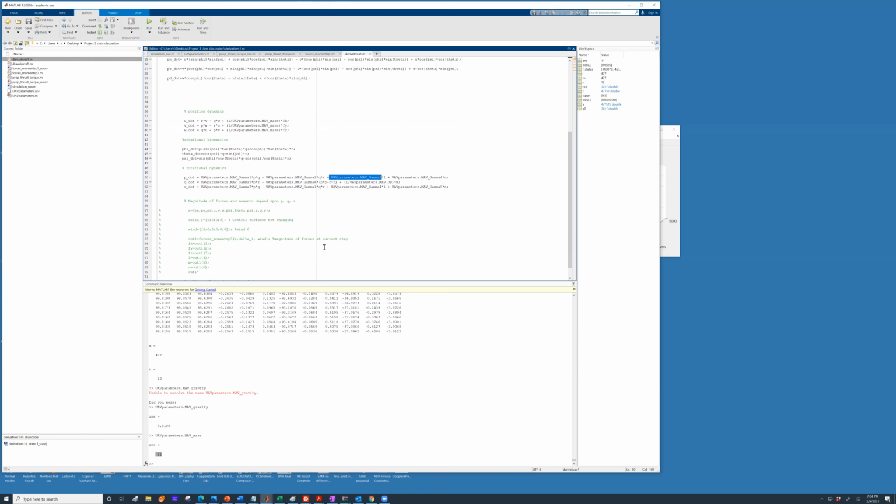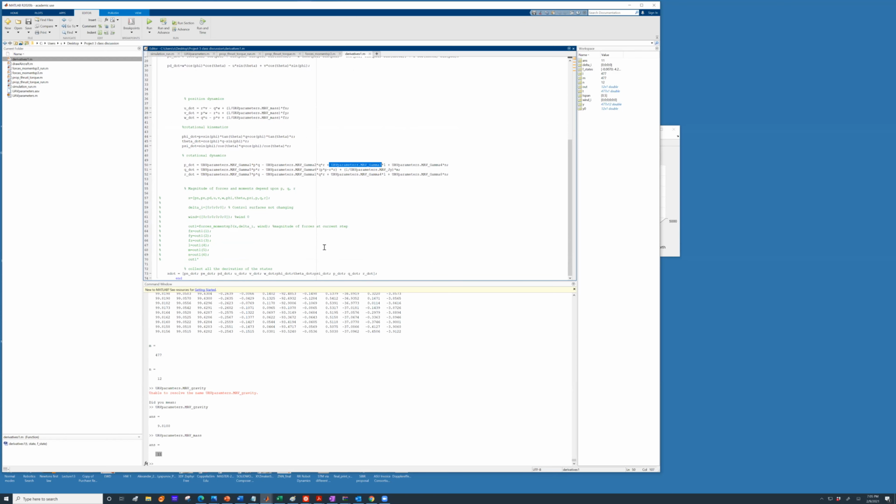Yes, that is correct. UAV parameters is the file that will store the parameters for your airframe. Which means your simulation code derivatives1.m doesn't have to be changed. You can just change the parameter file, and it will run for the different airframe.